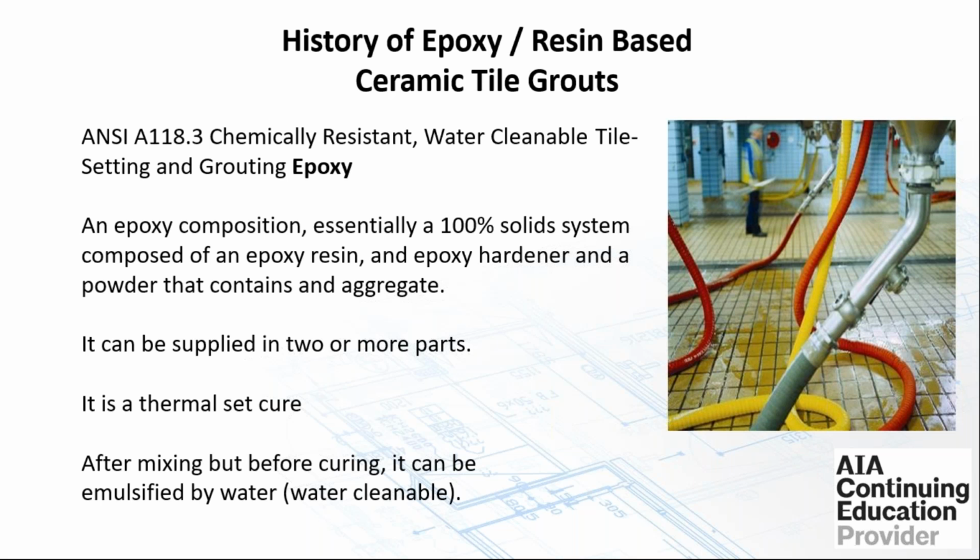Why is it important to be aware of that when working with these grouts? Once they're mixed, you need to get them out of the bucket, set them onto the floor, into the area where you're going to be using them, and spread them out so that they don't cure as fast as they would if you keep them in the bucket, where you have a mass that is putting off more heat. You can feel the bucket warming up if you leave it for a while. Get it out onto the floor and start spreading it out to make it easier to work with. After mixing, but before curing, it can be cleaned, emulsified with water, or in other words, water cleanable.